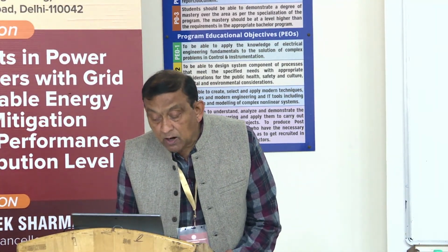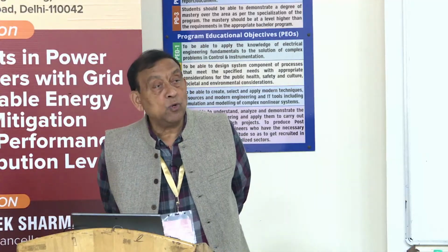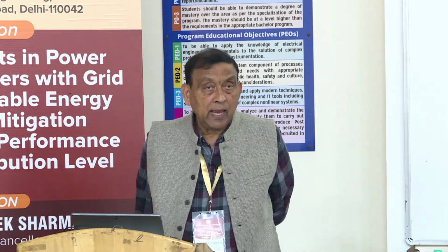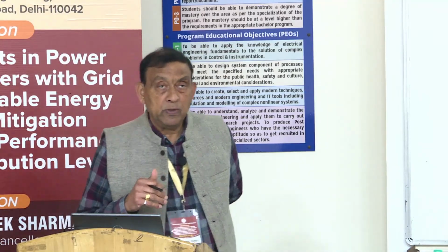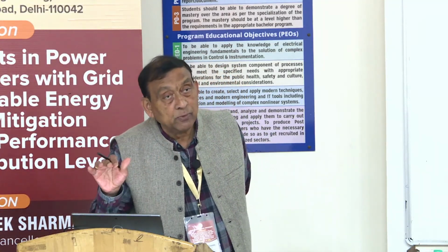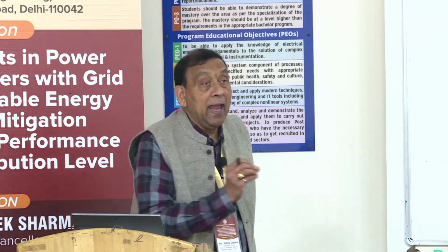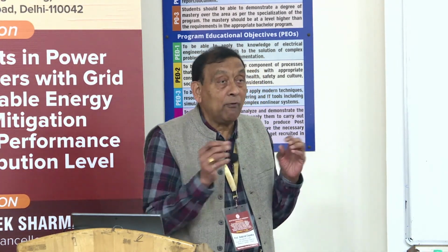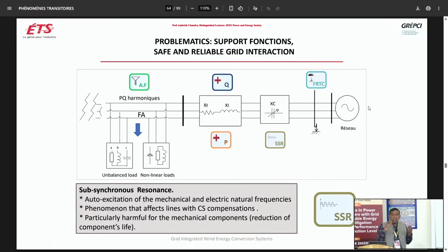There is a possibility of some subsynchronous resonance: resonance at below synchronous speed frequency. There may be exchange of power between the electrical transmission energy and the mechanical energy, and because of that oscillations will take place, and they are called subsynchronous resonance. Okay, so there is a possibility. It is particularly harmful for mechanical components.